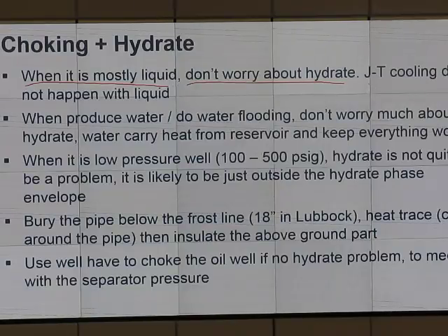JT cooling doesn't do anything, doesn't happen. When you have liquid go through the choke, of course you have pressure drop, but it doesn't cool or do anything. It doesn't have Joule-Thomson cooling. So if you have mostly liquid, you don't worry about it.